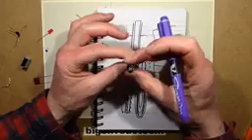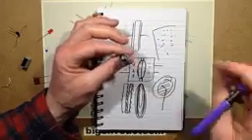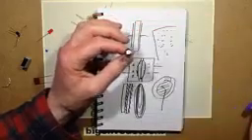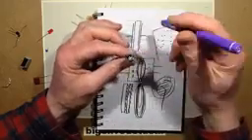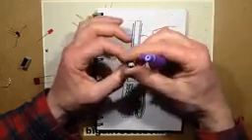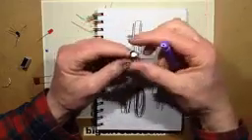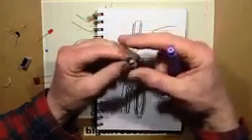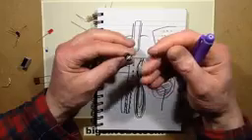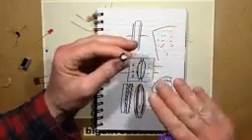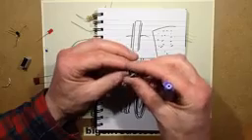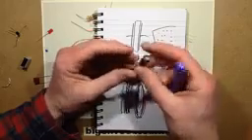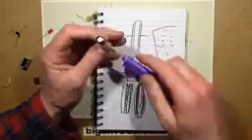Because traditionally, say for instance, all the old video games from the 80s tend to suffer problems after a while with what's called drying out of the electrolytics. They still measure the correct capacitance, but their equivalent series resistance, the resistance to current flow through them, changes, it increases. And what that means is that they stop doing their job properly.